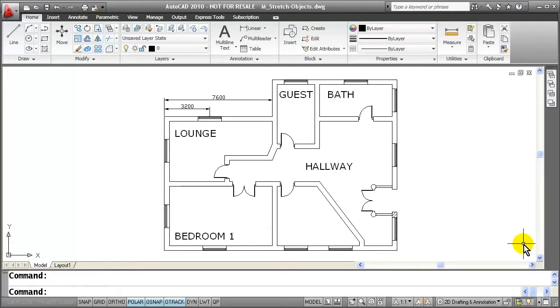So let's set the stage on what needs to be accomplished. Let's say that I have a drawing here that was started from scratch or from a different template other than my own. Either way, I would need to create a bunch of layers, set all of their properties like color and line types and so on, and then create all my text, table, and dimension styles, and multi-leaders. The list goes on. It is almost like rebuilding the template all over again. Let me show you what the Design Center can do for you.